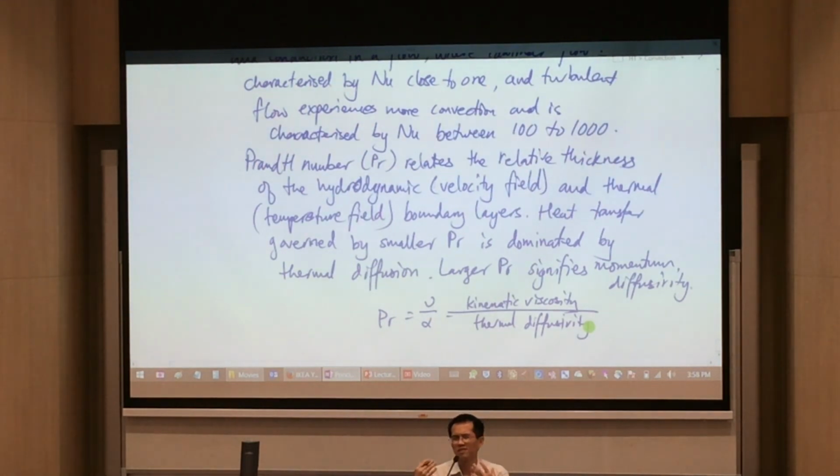So this tries to explain what is Nusselt number, and what is Prandtl number. You could copy that now, have a look again. Larger Prandtl number means that you have more kinematic viscosity side, or your thermal diffusivity is kind of like weaker if you have larger Prandtl number.